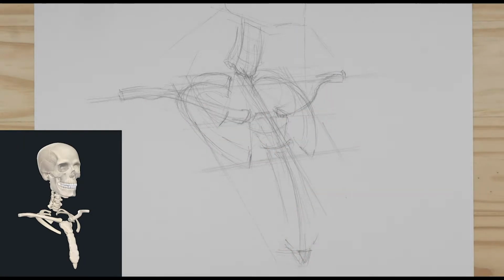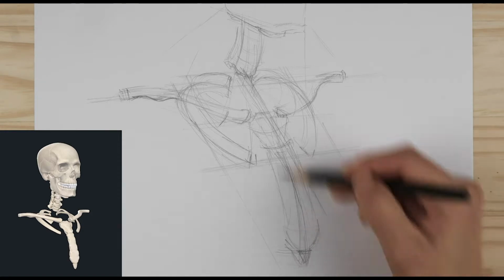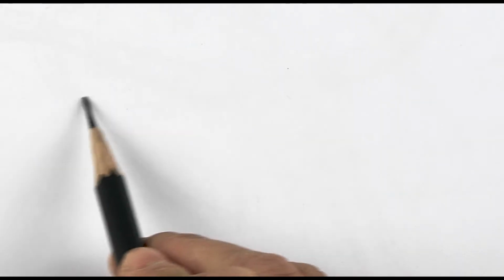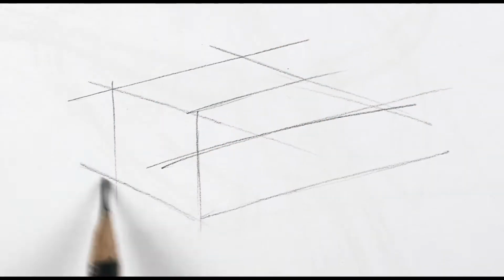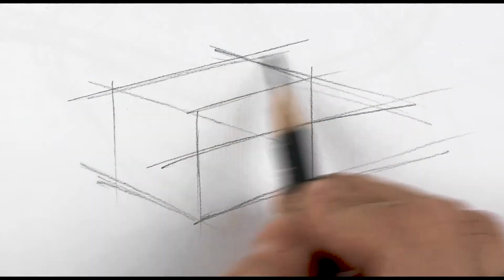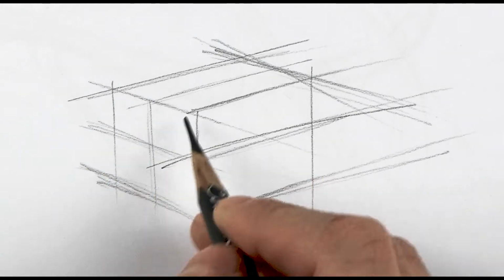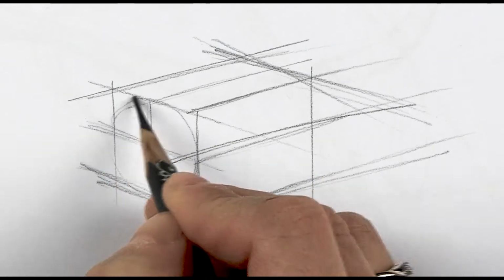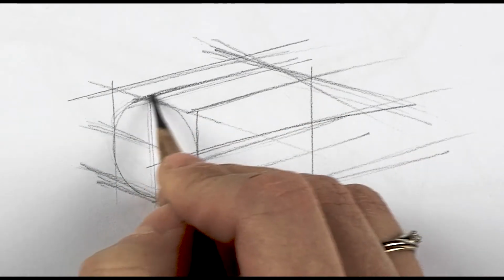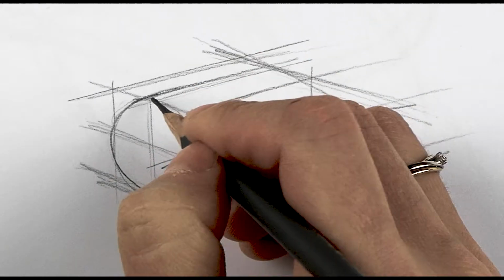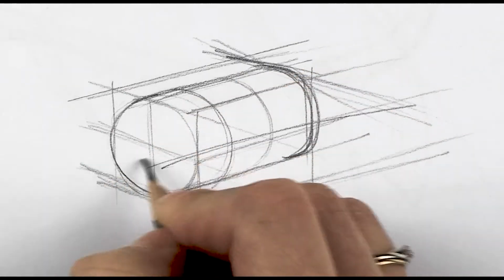Therefore, let's start with a simple exercise that helps you understand the spheres and cubic shapes. Draw parallelograms on 3 sides using obliques and parallel lines to create a cuboid shape. Then on one side of the cuboid, draw an oval following intersections that divide our cuboid into 4 equal parts to create a cylinder. Then draw curves on the cylinder parallel to our basic oval.